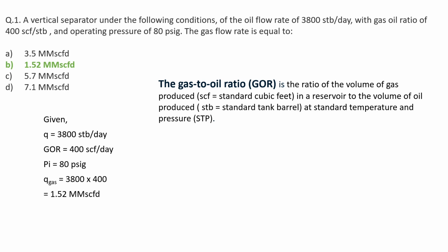So that's why, similar to the ratio of volume, we can also equate the gas to oil ratio to the volume flow rate. So here gas to oil ratio will be equal to the volume flow rate of the gas divided by the volume flow rate of oil. In the question they have already given the oil flow rate and we have to find out the gas flow rate with the known gas oil ratio. So that will be